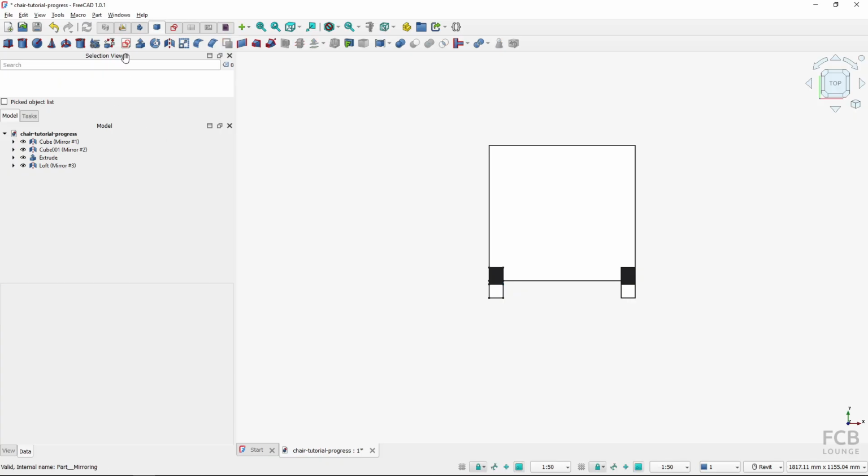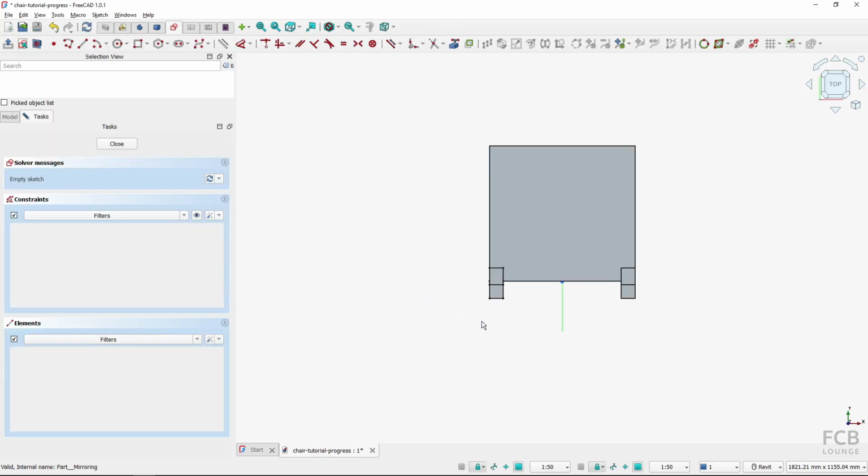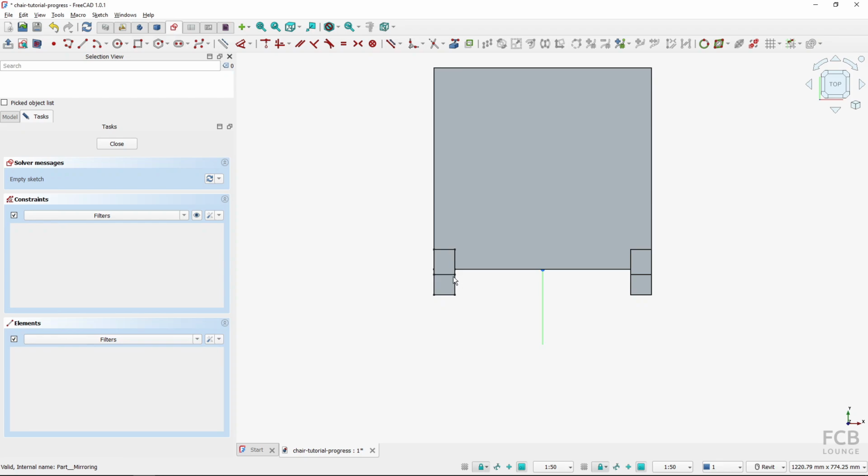So I will deselect everything and choose the create sketch tool, use the XY plane, hit OK. And now I want to use these two lines as stopgaps for my arc, which will be created like this. So I will import this geometry.